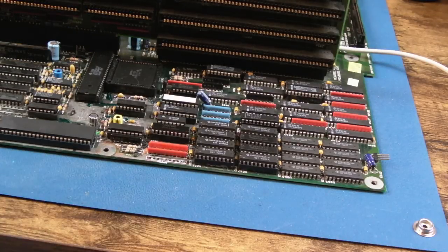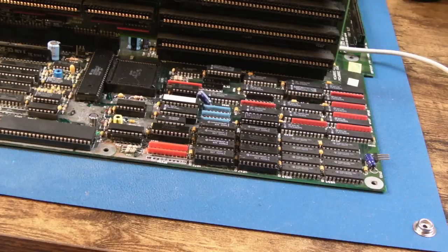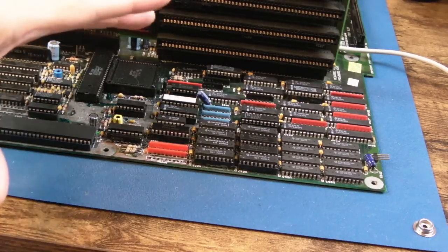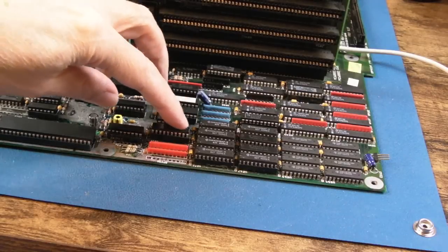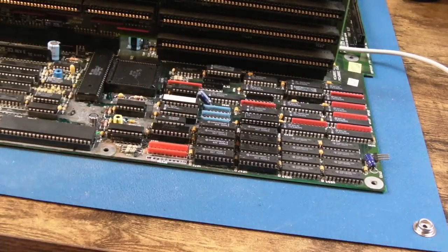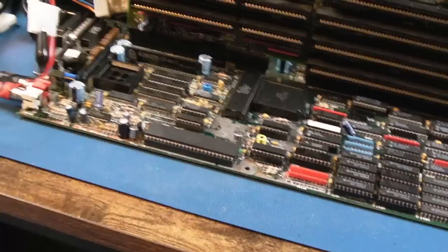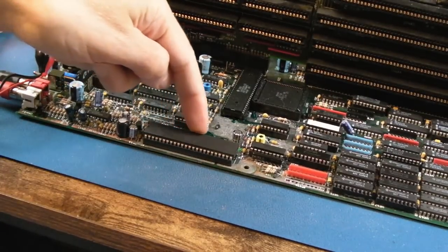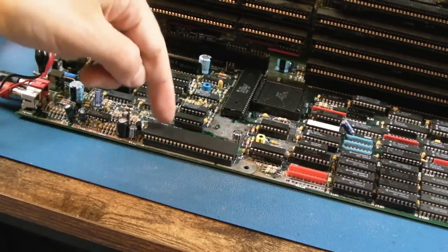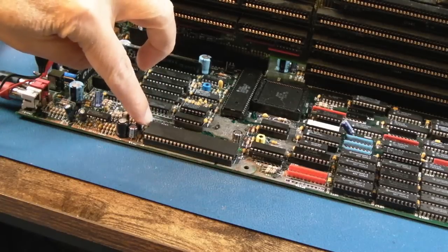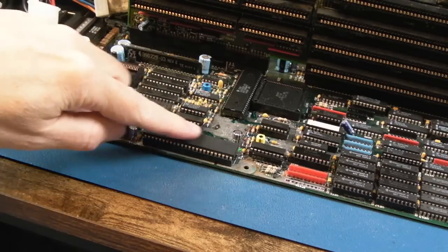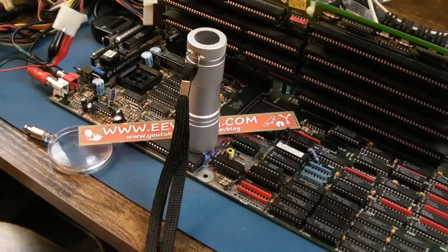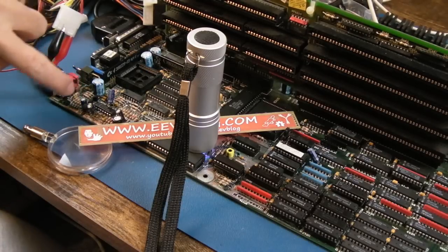So a number of issues caused me stress there, and obviously all self-inflicted really, just because it was taking so long that I started to cut the occasional corner, or I would stop at a point where I thought, right, I've got to fix that trace, and then I'd go away. Following day, forgotten all about it, didn't make a note. That was a good example of why one of the audio channels was missing. There's a trace that comes along here, and it sort of comes upwards at 90 degrees, and that trace is just balked, and I forgot to fix that trace before I fitted the socket. I presumed, perhaps in my mind, I thought I'll fix that later, and then forgot all about it. So this is why I had no audio on one channel to start with. So I just had a good scrub around with the fiberglass pen here on these connectors.